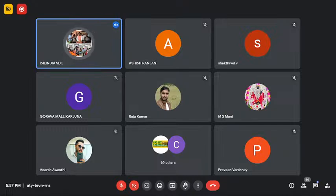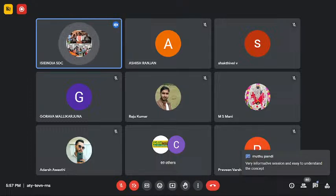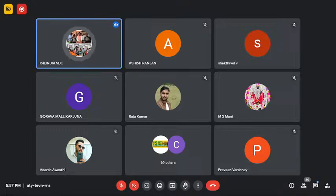And in case of fuel cell vehicle, the lifespan depends upon the fuel cell stack. Stack means the one which is generating electricity from hydrogen and oxygen. When you are supplying hydrogen, it is 100%, we can say it is pure. There is no chance of dust accumulating inside because the thickness of one fuel cell, which is developing one voltage, is almost 1.1 mm. So we have around 300 cells serially connected, like that stack we are using.